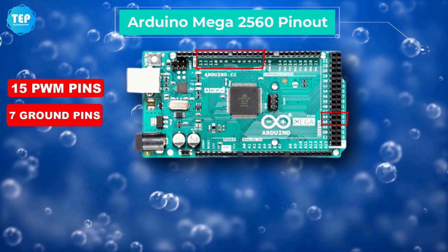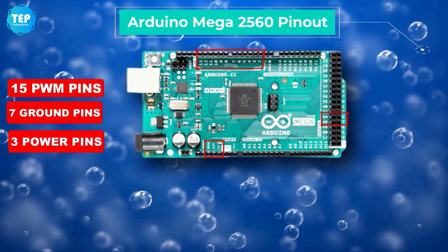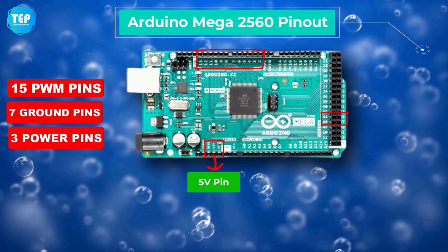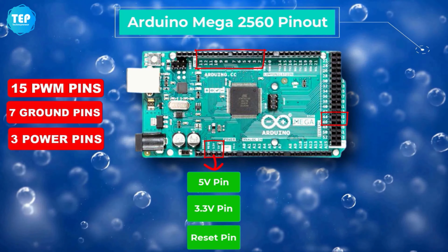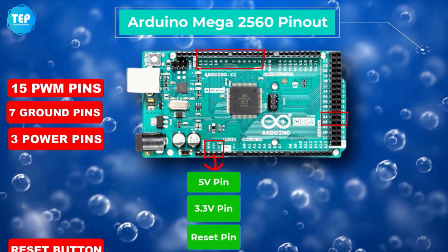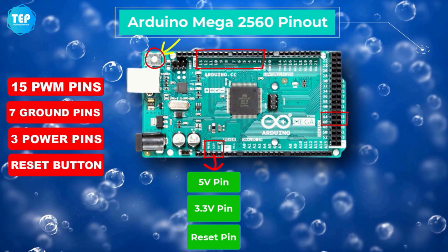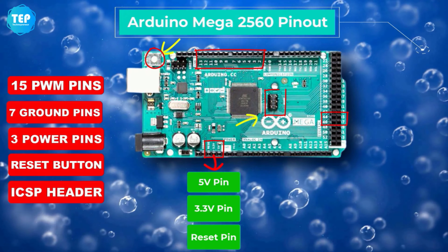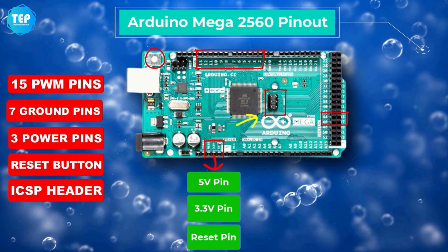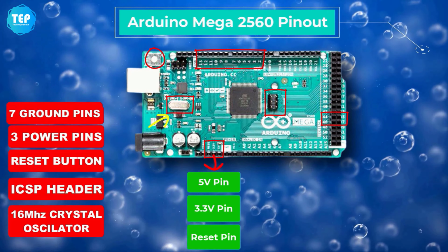I have encircled them. It also has these 3 power pins, Vin will provide the input voltage. Then we have 5 volts pin and 3.3 volts pin. It also has 1 reset pin, which is used for resetting the board programmatically. Making this pin low will reset the board. There's also a reset button present on the Mega board. Moreover, it also has an ICSP header for connecting third-party modules. Arduino Mega comes with a crystal oscillator of 16 MHz.